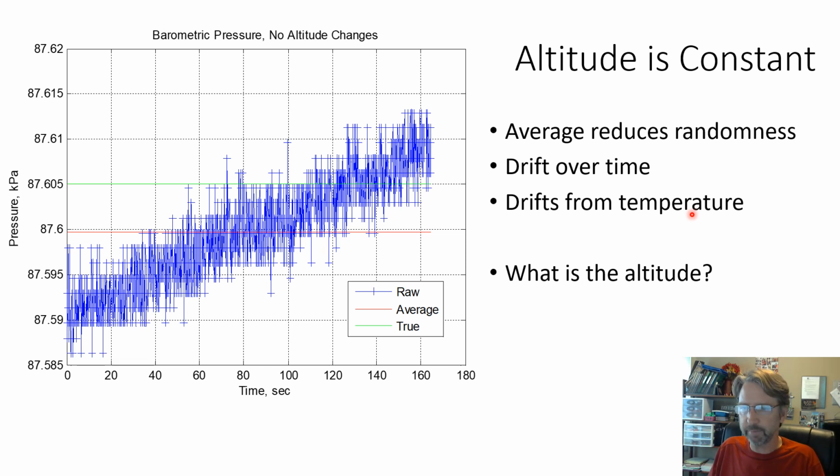And we would always have it grab the pressure on the ground as the 0 altitude, to use that for landing. So the worst thing that would happen is if you flew for an hour, sometimes you would get 10 feet of drift in the altitude, and it would overshoot or undershoot the landing because the glide slope was fairly shallow. So that was the only problem we had with this altimeter, and it worked really well otherwise. So we just went with it and had long runways. You could do other things like radar and sonar and stuff, but we didn't need to.